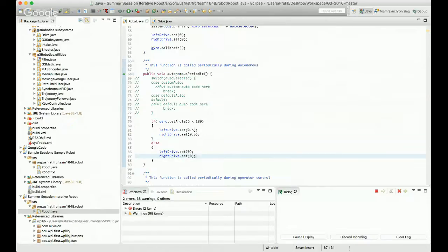So in our specific case, our robot would probably turn anywhere between 190 and 200 degrees when we wanted it to turn at 180. So there's a couple ways to handle that. You could always just change this 180 to, let's say, like 175, 170, maybe even 160, depending on how fast you're turning.